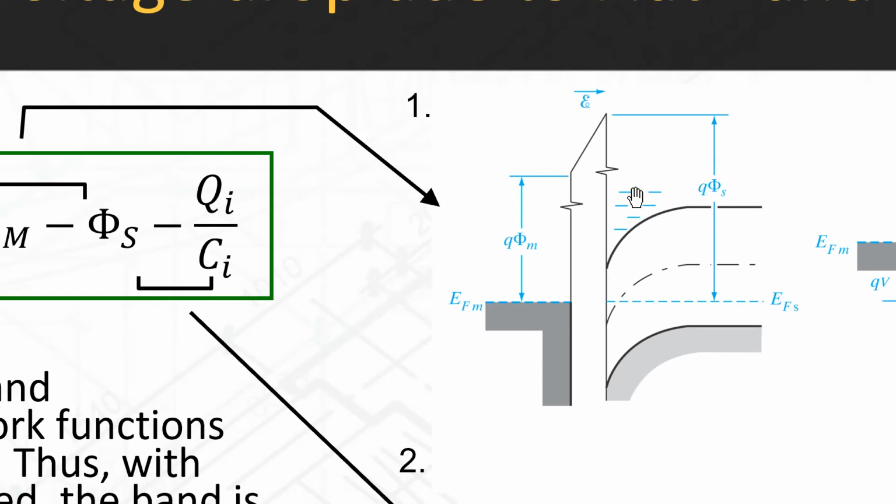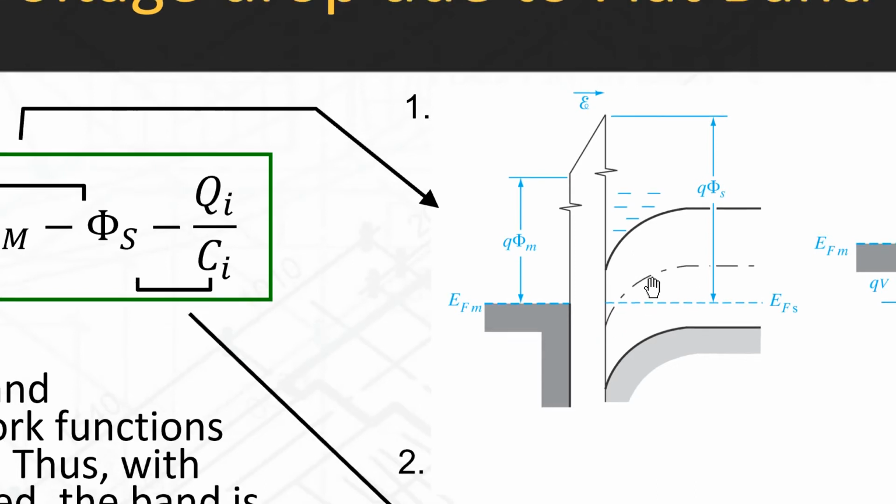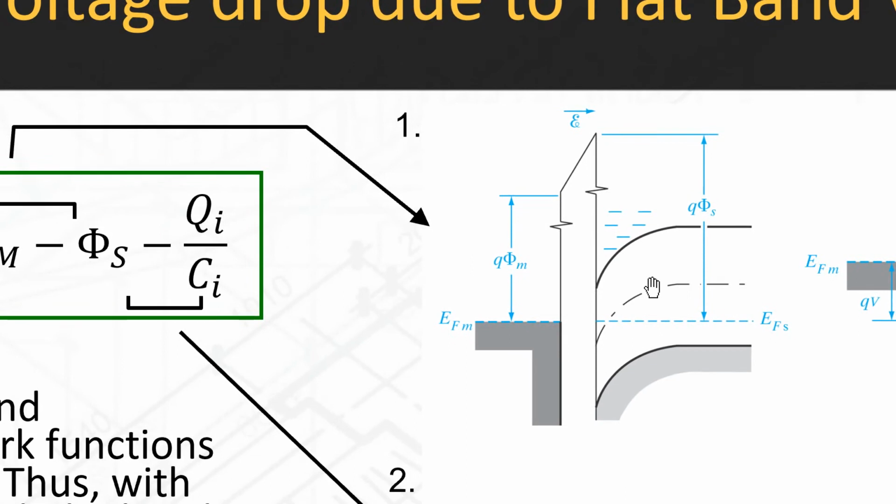If you have a bunch of electrons here, and notice that EI is less than EF here. Do we have inversion here? Yes and no, I heard both. Why or why not? Let's talk about that. Since there is a bending greater than EF, there is an inversion. Yes. Exactly. Because this band has bent enough where now you have inverted the material, meaning it's below EF. So that means, yes, you have an inversion channel there.